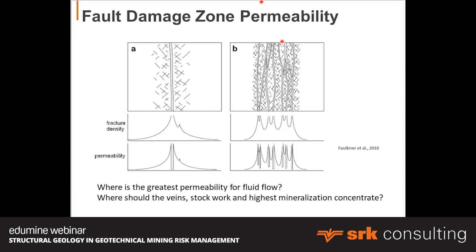So, a nice simple illustration of permeability of groundwater along faults, and here's the fault core and there's a damage zone. Here you've got many fault cores with an extended damage zone, or influence area, around those faults, and as the fracture density increases, so does the permeability. Often right on the fault core itself is a lot of clay and the permeability drops to something negligible. But those damage zones are fundamentally important in terms of understanding groundwater flow and even in terms of rock mass strength.